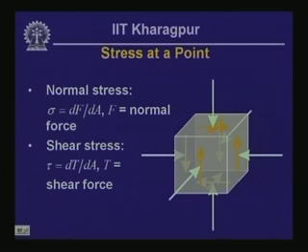And finally, we are going to have 4 more shear stresses, and now our description of the state of stress of this particular point enclosed by the small infinitesimal cubical element is complete, and what we have here are 3 components of normal stresses, and what we also have is 3 more components of shear stresses and their complementary counterparts.